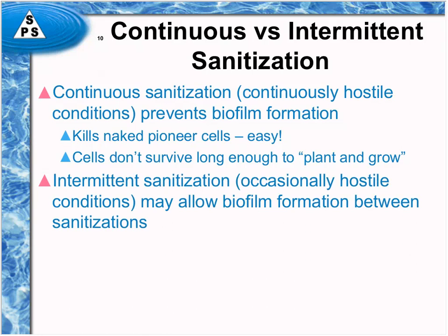So when the sanitization conditions are not present, and it's more ambient type of water, that does allow biofilm to start forming. And so depending upon how long that period is, will determine how much biofilm actually is allowed to form between sanitizations. Now, that's a very, very important concept you need to grasp, because that becomes the factor between whether a sanitizing event is going to be successful or not.